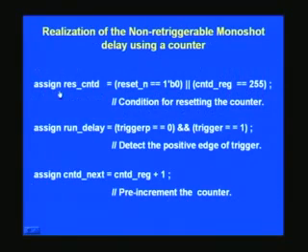So once again we have an assign statement for resetting. That's also a register as such. So here we have combined. Earlier I said we should avoid else statements not to cross 5. So here probably it crossed by 1. So I have combined two similar statements right outside here, and notice that there was an asynchronous reset when it is 0, and then counter value also does the same thing of resetting the counter itself.